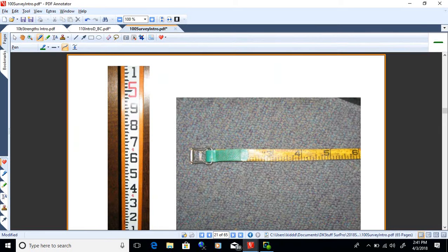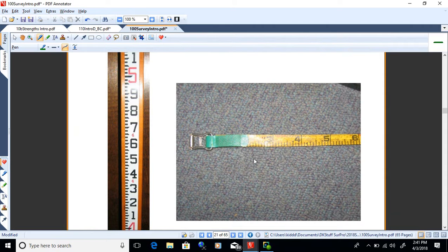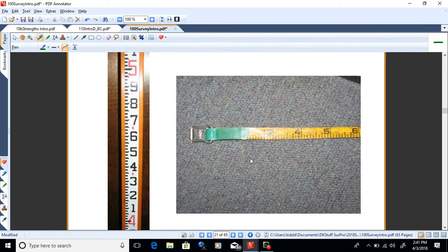And there you can see some equipment. You see it's broken up into decimal feet. Okay, see the level there, or the rod? We've got the red numbers are even feet. So I got 4, and I got 5. And then I got 1, 2, 3, 4, 5, 6, 7, 8, 9, and then I go to 5 feet. See, those divisions between like the 8 and the 9, those aren't inches. Those are 1/10 of a foot, is what they are. A little bit longer than an inch, okay?